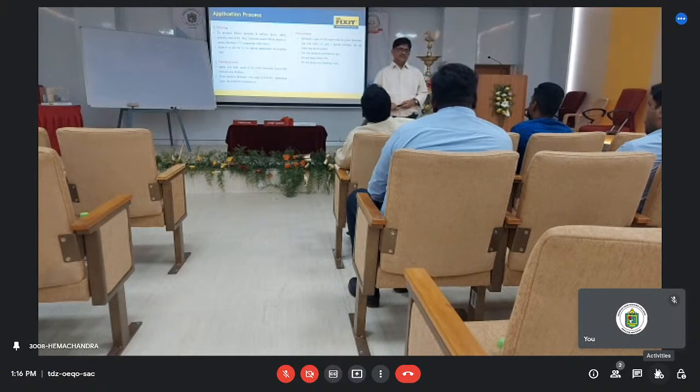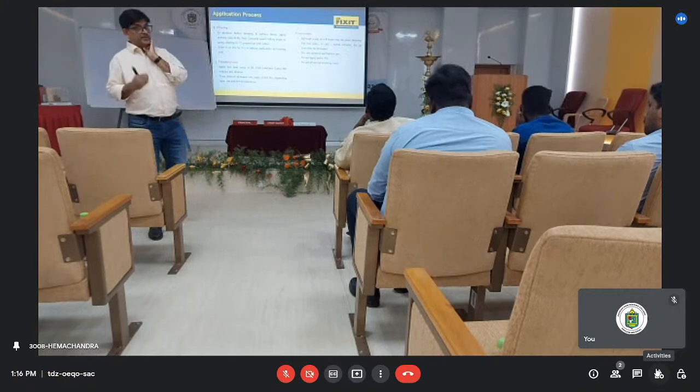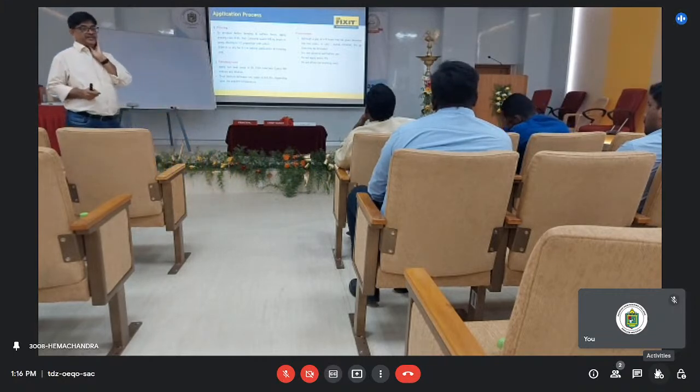Systems are available with everyone. They are not very different, but it's a breathable coating also. Breathability is important in a coating system because it should allow the moisture to go. Every weather-resistant coating has to be breathable. Otherwise, what will happen?